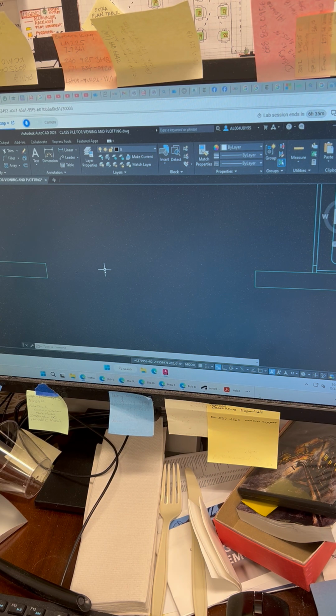Then click on it. The boldness lets you know that if you were to click, you would be selecting that element. With that element selected, here is the erase button here in the modify panel of your home tab, or you can press delete on your keyboard. That'll work also.